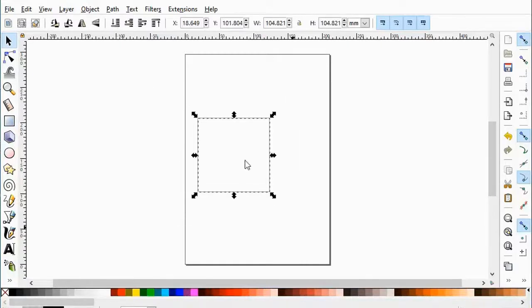As you can see up here, the dimensions on the width and the height are exactly the same, but we're going to change this to inches as I mentioned before. So oh my God, we almost had it exactly right. It's 4.127 by 4.127. So let's lock our aspect ratio. We lock our aspect ratio right here. If we change something in here, it'll change over there. So it's a really fun tool. So I'm going to change that to 4. Type in 4, click enter, and as you can see over here, it changes too. And so now we have a 4-inch by 4-inch square.